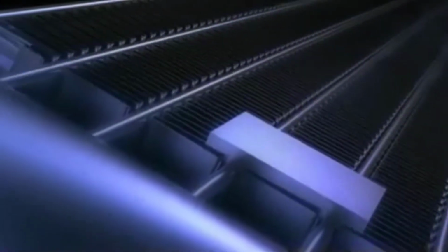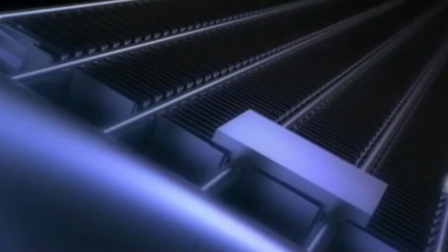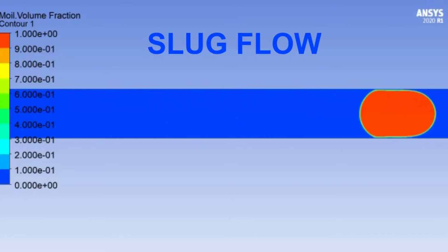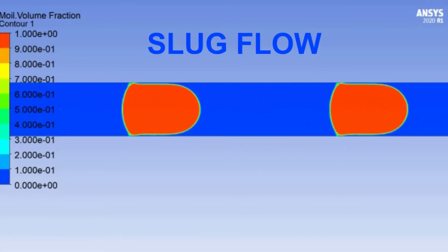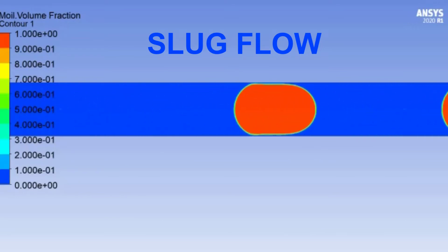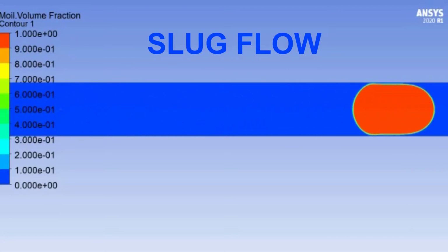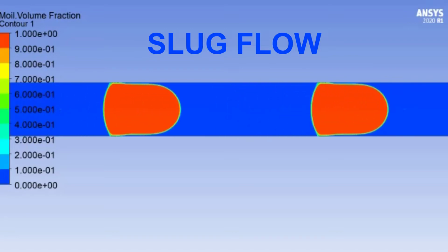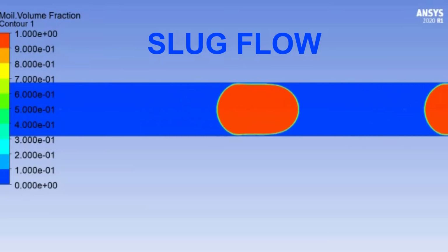Since microchannel heat exchangers are completely changing the world of cooling systems, we have developed a nanofluid-based slug flow in microchannel, considering the higher bulk thermal conductivity of nanofluids. Slug flow is a mixture of two fluids in which large bubbles of secondary fluid are presented in the primary fluid. With the internal circulation in the mixture, it can remove more heat. Here we will use nanofluid as one of the fluids in the mixture.